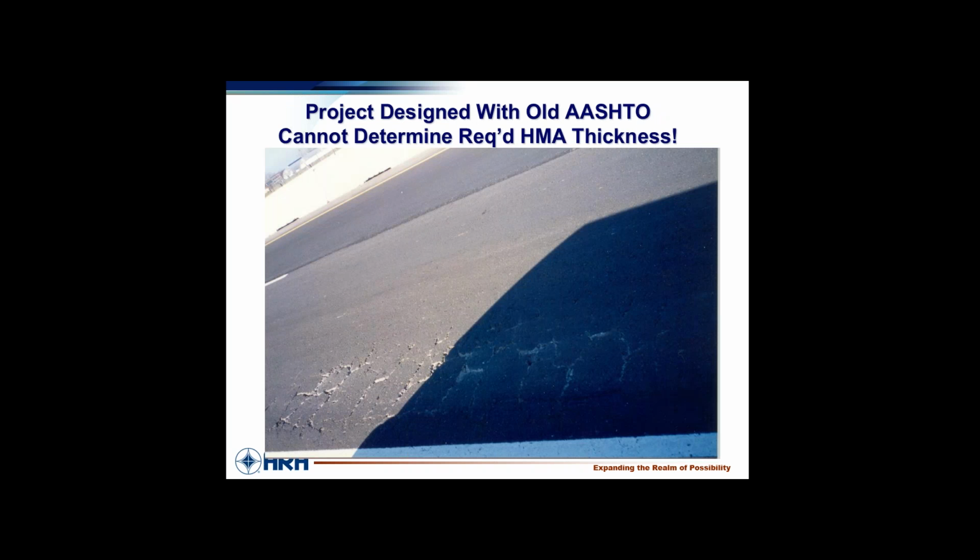I've somehow lost a lot of my pictures, but this is a truck lane. Well, they're both truck lanes. There are so many trucks. And you can see the alligator fatigue cracking, mostly bottom up, I think. And that just started profusely and went on and on and on.